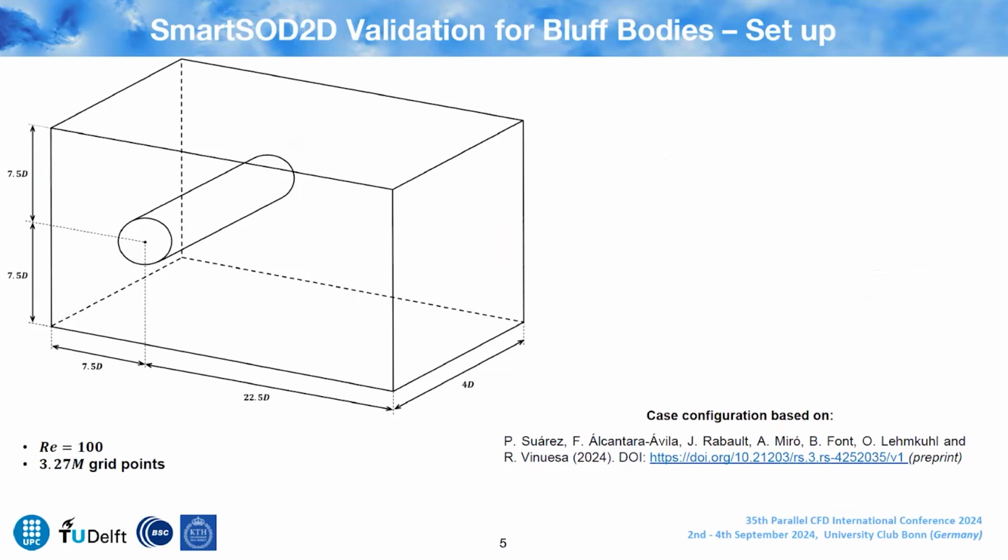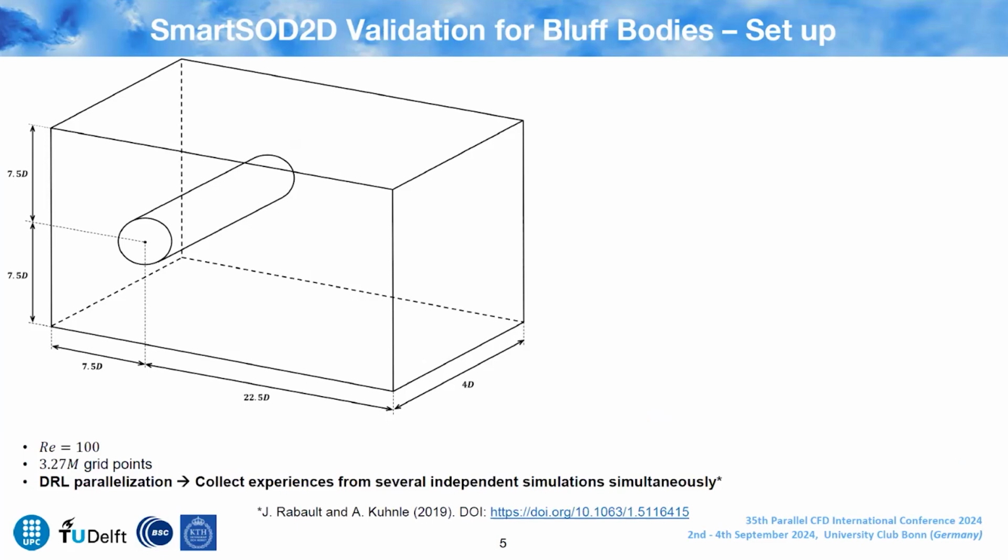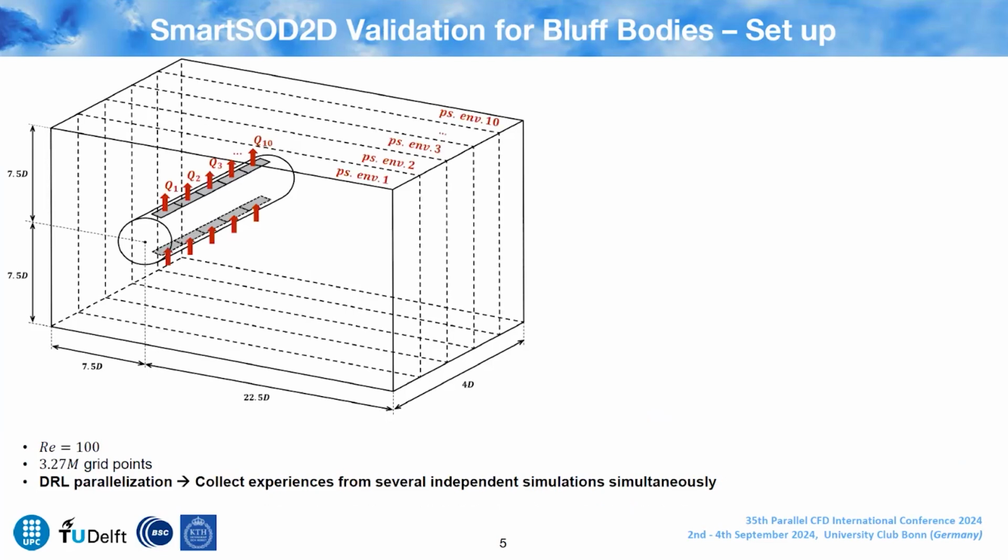And in this case, as I've told you before, the most time-consuming part is to collect experiences from the CFD environment. So to accelerate the training, we are using a DRL parallelization that was proposed in this work so as to collect experiences from several independent simulations simultaneously. So for instance, the cylinder domain along the invariant direction, we can divide it in several pseudo-environments.